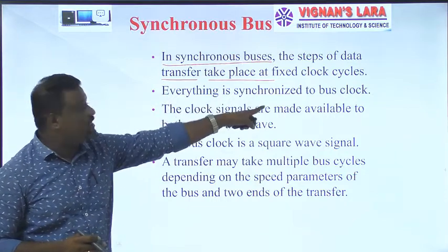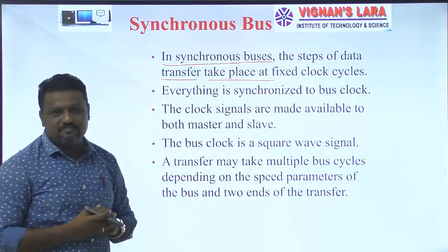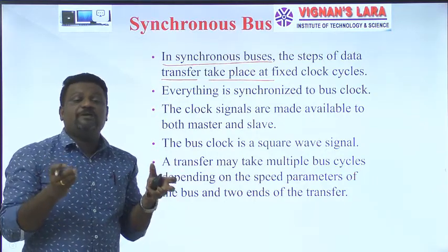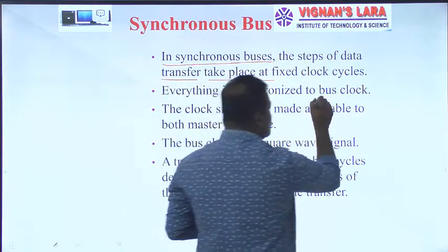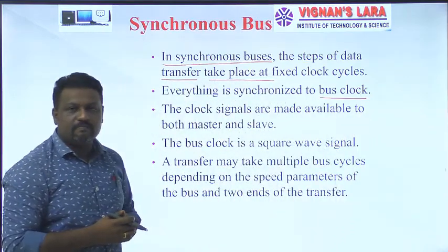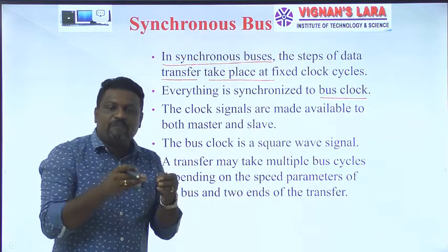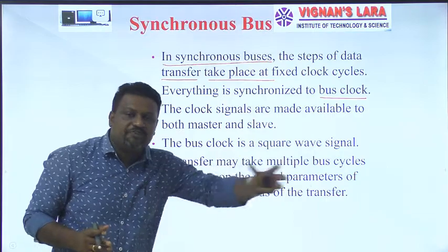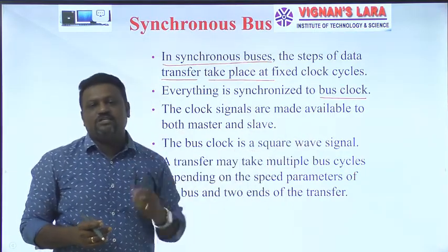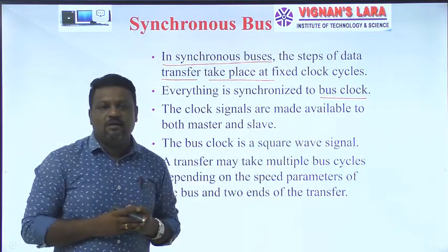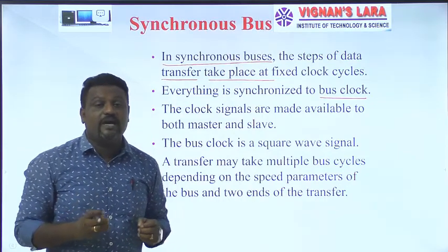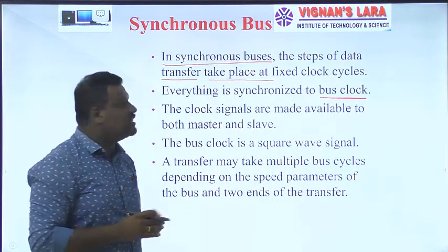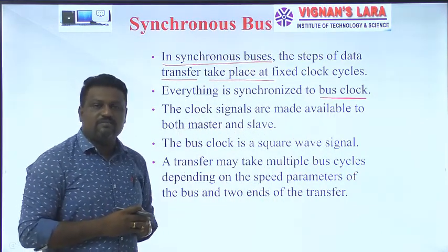Everything is synchronized to the bus clock. That means whatever operations we are going to perform by using a bus must be synchronized with the bus clock. This is very, very important. What operations do we perform on a bus? Either sending an address, or sending data, or sending control signals, sending request signals, sending acknowledgement signals. All these signals must be synchronized with the bus clock. That is the second thing you have to remember regarding the synchronous bus.